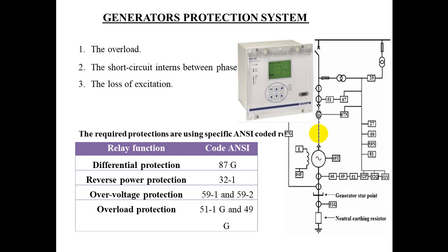Protection against loss of boiler firing. Two methods are available for detecting the loss of boiler firing. In the first method, normally open, or NO, contacts are provided with the fan motors, which may trip the generator if more than two motors fail. The second method uses boiler pressure contacts with a load generator.